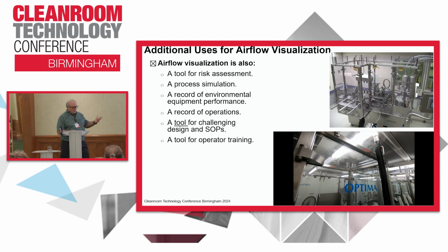It's a useful tool for risk assessment, for process simulation. When we do our smoke studies, our airflow visualization studies, we're meant to do all of our interventions, all of our aseptic activities, and we're intended to do those under smoke. And we do those for a variety of reasons. One is to understand the design, but two is to look at the operator's movements. It's also a record of environmental equipment performance. It's a record of your operations. It's a tool for challenging design and SOPs, and it's a tool for operator training.